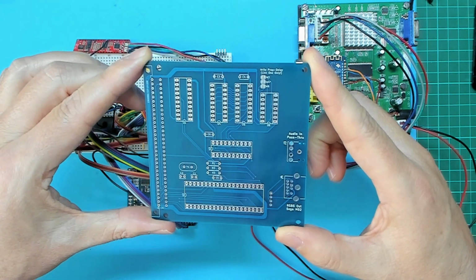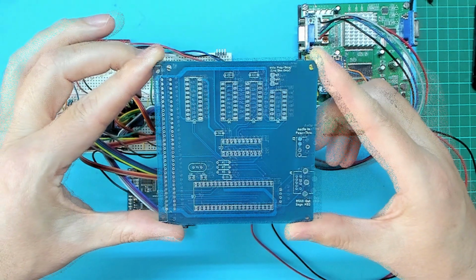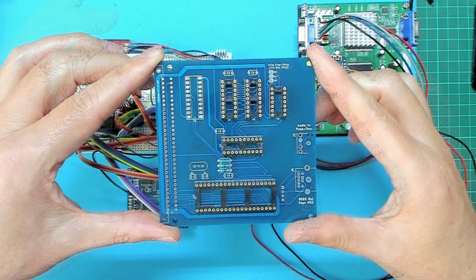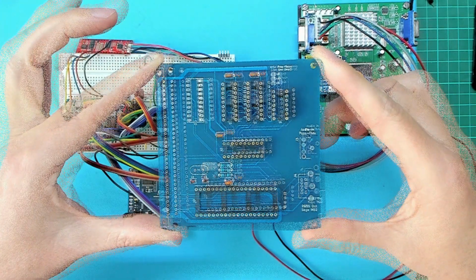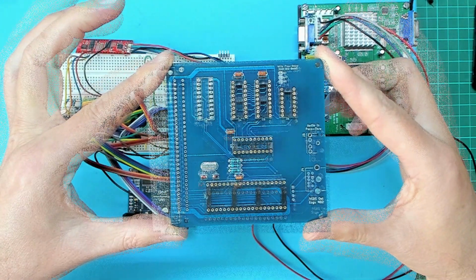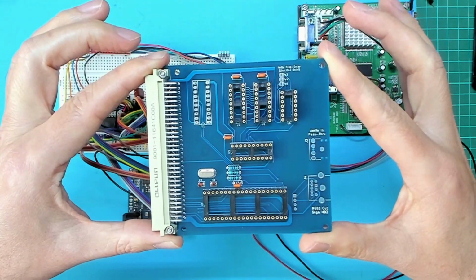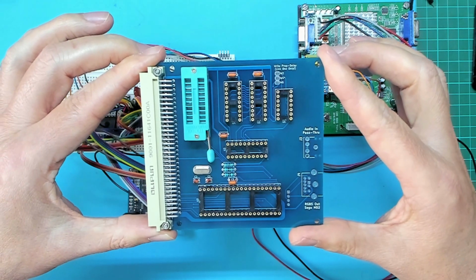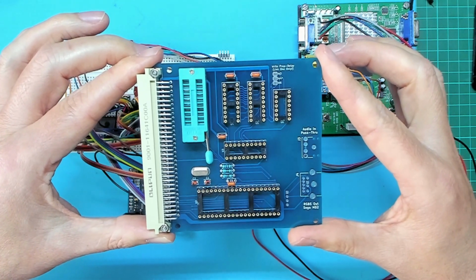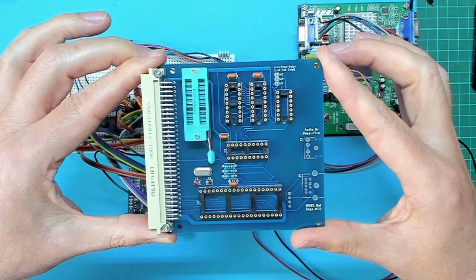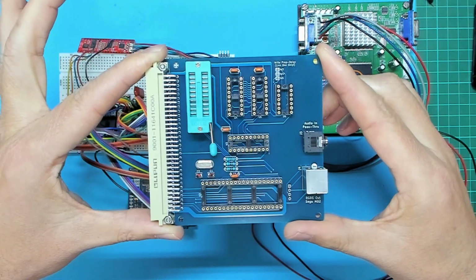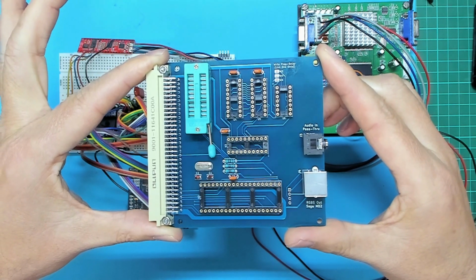So let's put the first one together. I'll start off with the resistors and then insert the regular IC sockets. Then I'll fit the capacitors and the crystal, after which the DIN 41612 MECB bus connector and also the zero insertion force IC socket that I'm going to use on this board for easy swap outs of the address decode PLD chip. Finally, we'll solder in place the video and audio connectors.